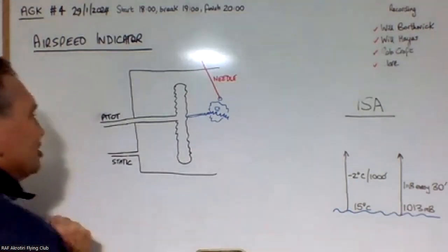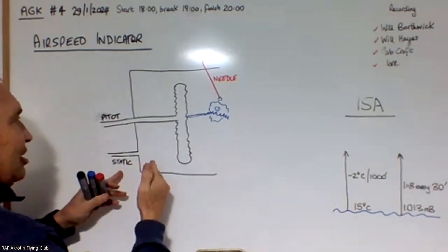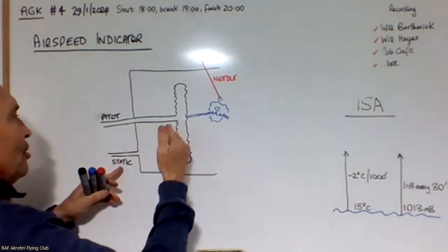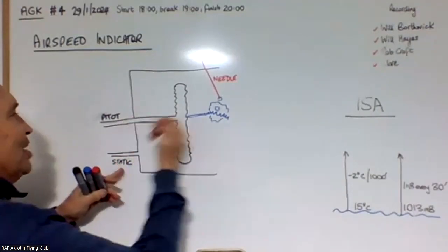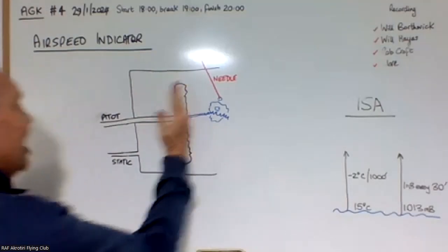So what happens is that you can probably see that the difference between the static and the pitot pressure is causing this capsule to expand and contract.